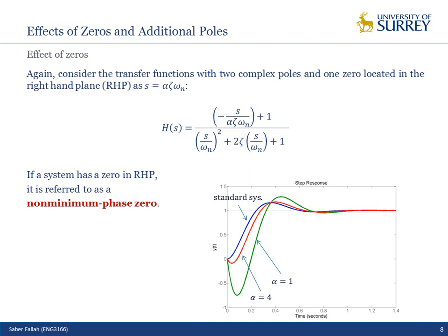Okay? How does that response actually look like in real life? This one? What do you mean, how does it look? For example, it starts this way. If you have the spring damper I showed you, you would like to start from the right-hand side, but you start from the left-hand side. And instead of having overshoot, you have undershoot. It gives you a totally wrong direction, which is not desirable. Okay?